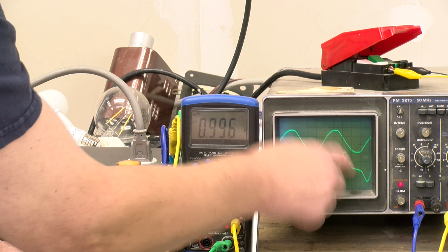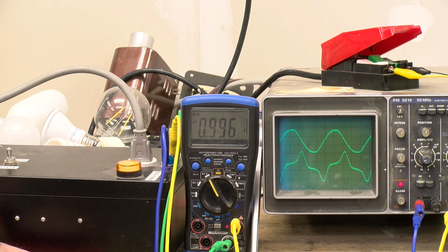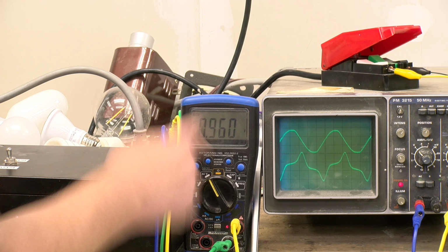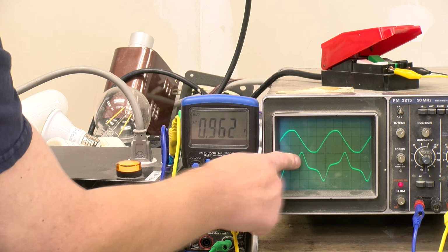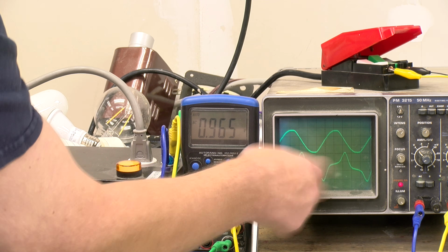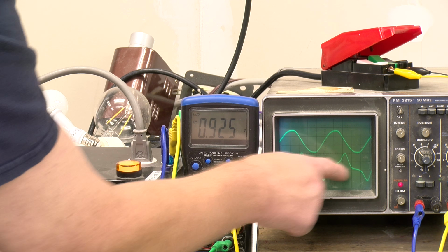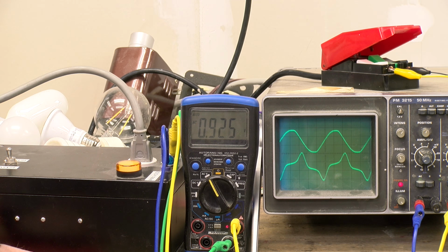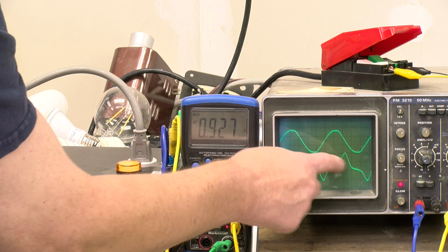It's not as jagged as some of those electronic power supplies, but it certainly will not be ideal for the power system. Now, this isn't as bad as it looks, because if we look here, the RMS current here is about an amp. Well, for a 1 kilowatt transformer at 120 volts or so, we would expect 8, 9, 10 amps flowing under full load. So this really would be pretty much disappeared under the situation where the transformer is really designed to be operated. So it's not that much of a problem.